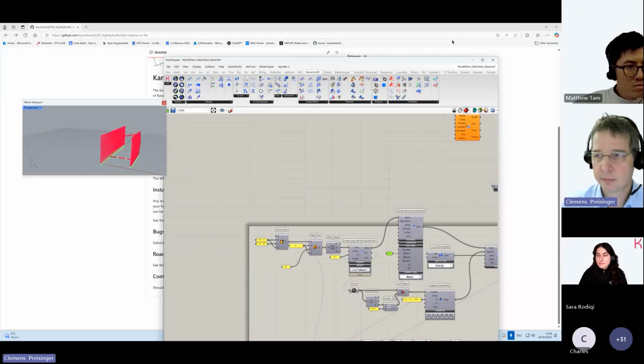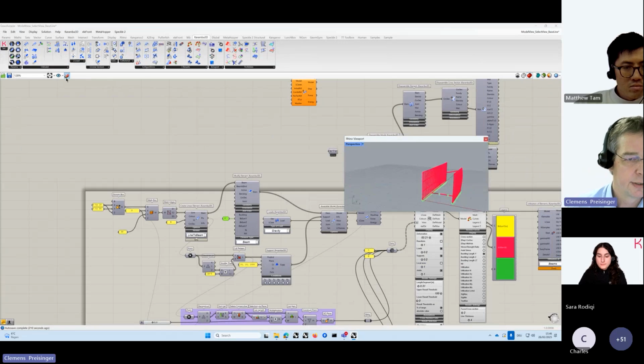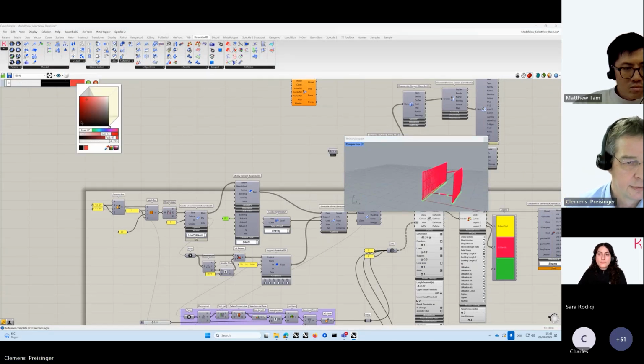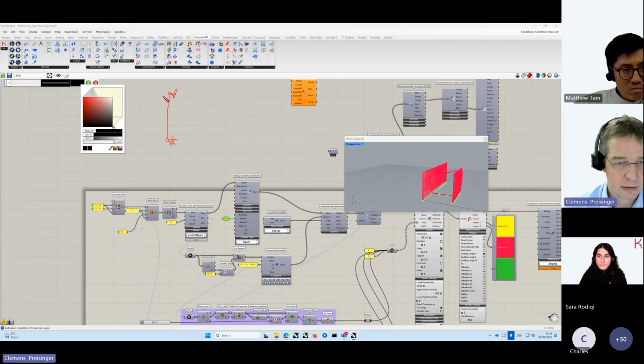So, for example, there are these classical so-called Euler cases. If you have a column which is hinged on one side and then straight down, also hinged here, and then here fixed, then it will buckle like this, for example.